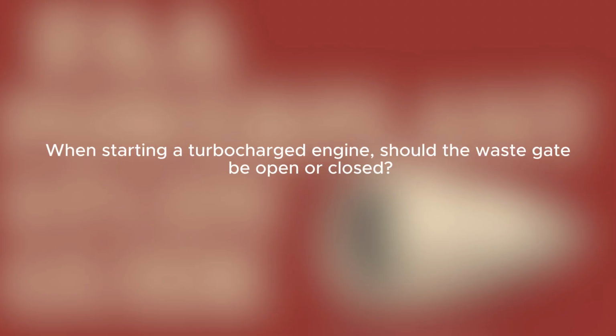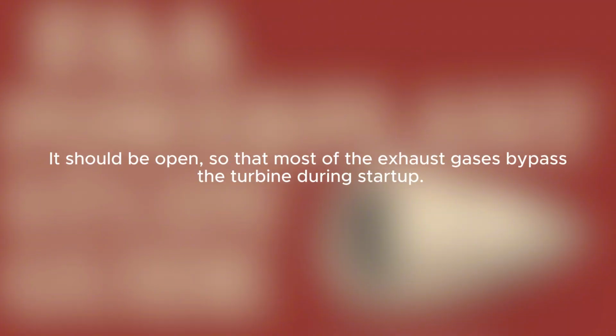When starting a turbocharged engine, should the wastegate be open or closed? It should be open so that most of the exhaust gases bypass the turbine during startup.